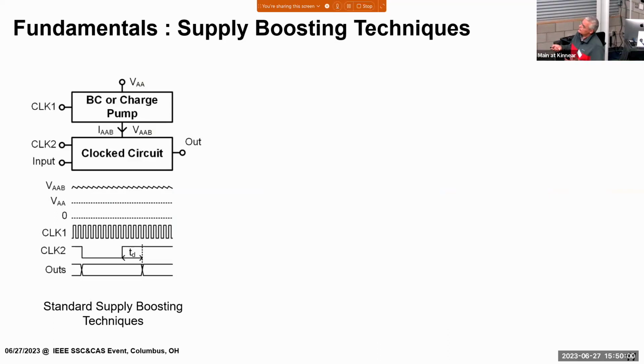you have a clock which runs at a higher frequency than your operating frequency. It doesn't have to be a clock one. It can be an analog one, but you have to have some kind of circuit that is clocked faster than the bandwidth of your circuit operation, and be able to maintain this voltage level constant, okay? Like the power and the volume, you try to maintain the same level by burning some power here, wasting power actually, and you have to operate your circuit at lower speed than the clocking speed of that power generation system. Okay, so that's a standard approach.